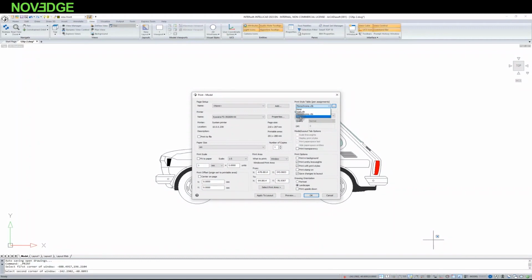So in the Windows documents, there to the INTERsoft IntelliCAD 2023 catalog and subsequent numbers, as later there will be subsequent versions. And of course, also earlier versions, if you have them, respectively 2021 or 2022. If you add your own templates from the program, it will automatically be easier to find. Now I'm choosing here that I'm going to print in the same colors that were chosen here. I'll be choosing element thickness from elements, so I have it checked here. I can still show if the orientation is portrait or landscape and check the preview.